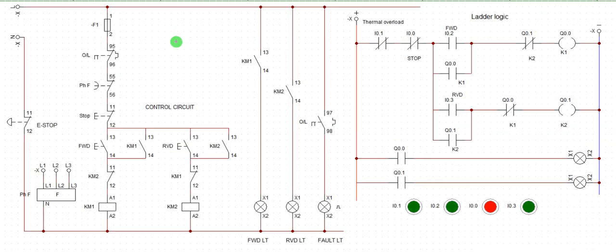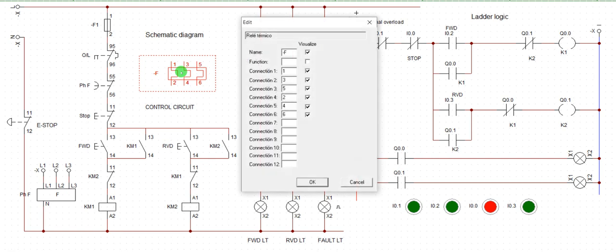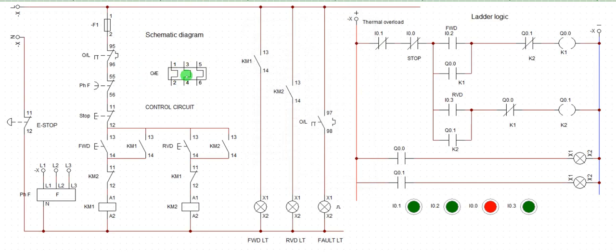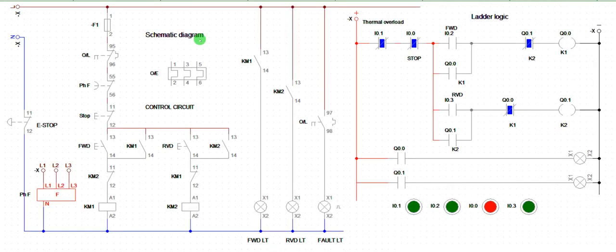This is the overload block. So we're going to have something like this. This overload block is one having this auxiliary contact. So until this one is getting energized, let me see if we can simulate it now. All right, when this one is activated, that is when this one will get de-energized and this one too will get de-energized. Okay, but I don't have the power circuit now. All right, okay, it's even working now. Look at it, it's working. It's now deactivating here and yet coming out this one.